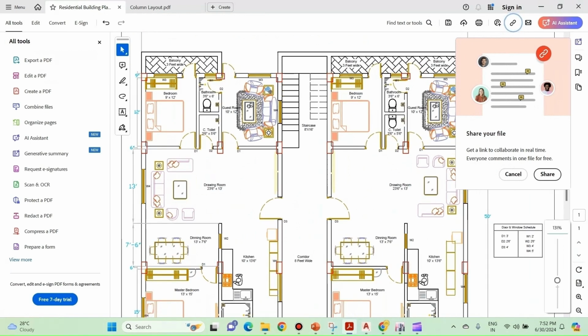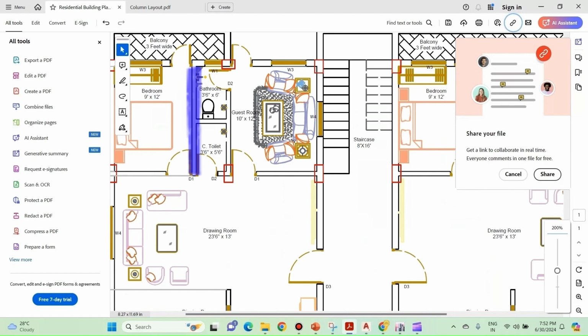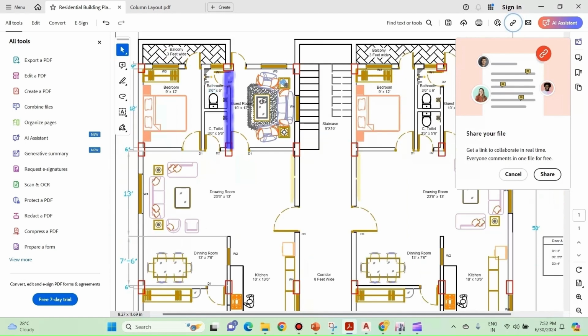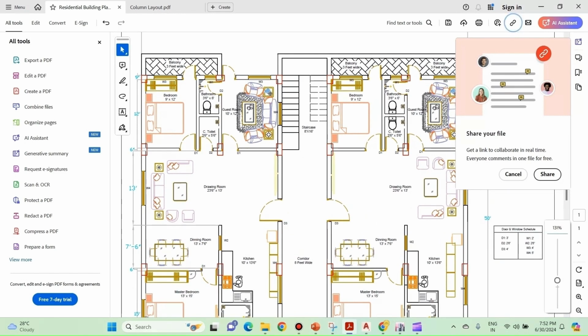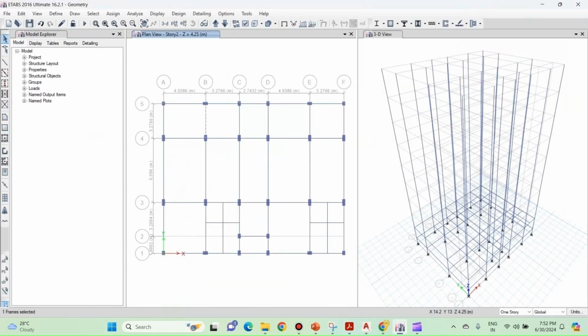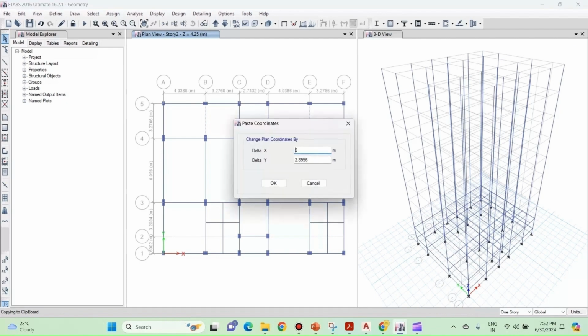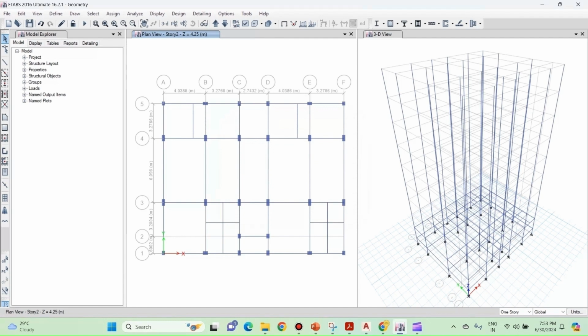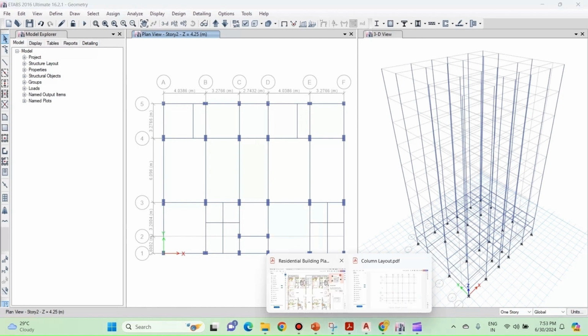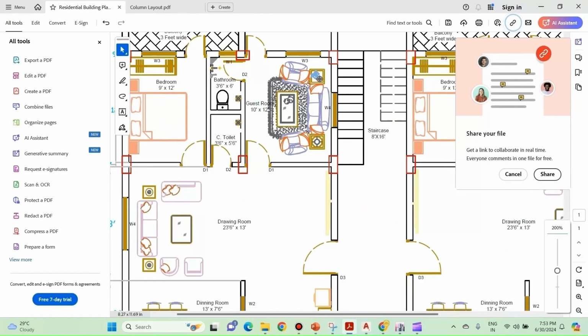We need to add a beam to support this internal wall as well, which is at a distance of 3 feet 6 inch and 3 inch and 3 inch from this side, so total 4 feet. So we need to copy this beam at a distance of 4 feet on the left hand side, and similarly for this bathroom as well. Okay, so select this beam and this beam, Control C, Control V. This time in the negative x direction, it will be minus 4 feet times 0.3048. Press OK, and we can ignore this beam which is of length 3 feet 6 inches.